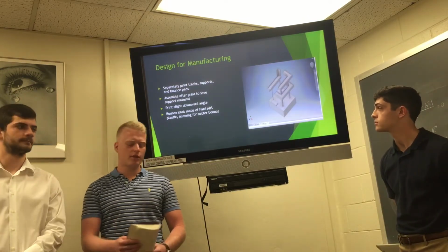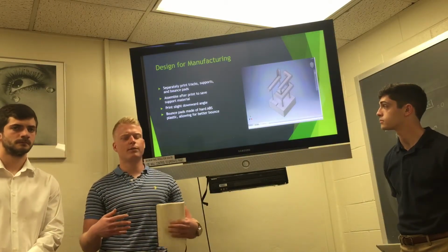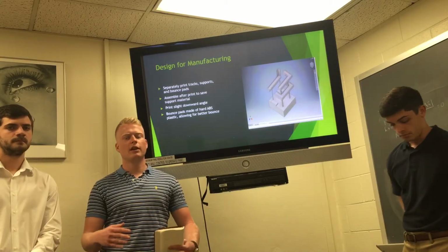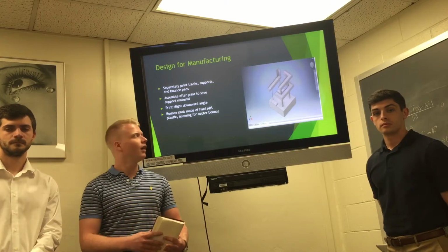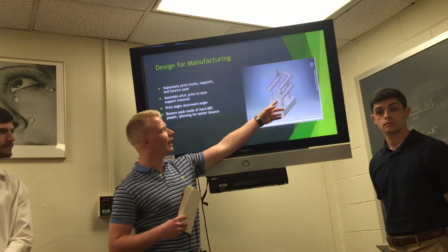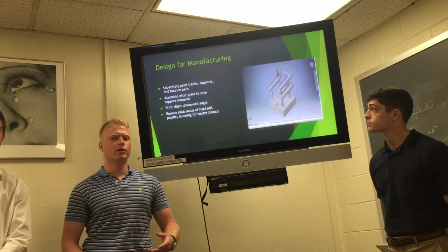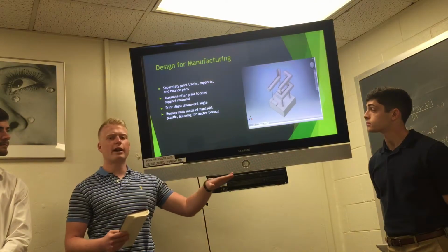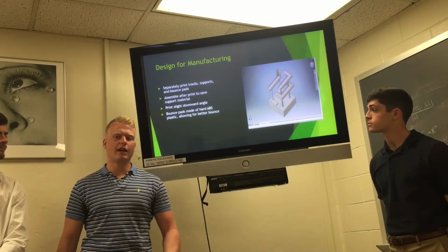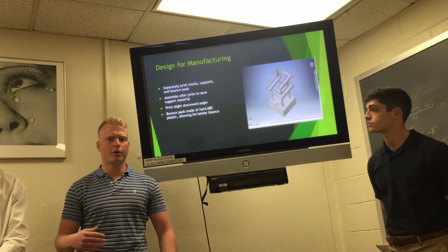So for the second station, we chose the bouncer option mixed with the catapult, and for this we decided to 3D print the tracks, the supports, and the bounce pads all separately, and then assemble them ourselves after the printing. This will cut down on the large amount of support material it would take to fill these large gaps right here, and thus save us money in the long term. We will also use a 3D printer because each track has a slight downward slope. That would be easier to 3D print as opposed to making that ourselves. And the hard plastic bounce pads that the printer will print will provide a more efficient bounce for the ball.